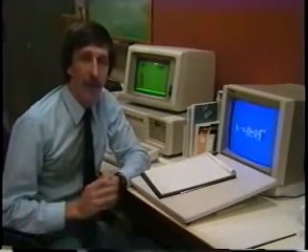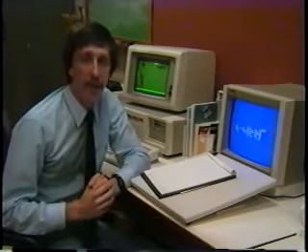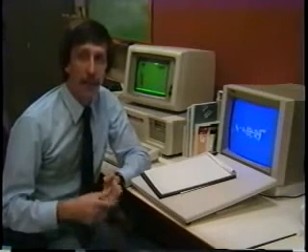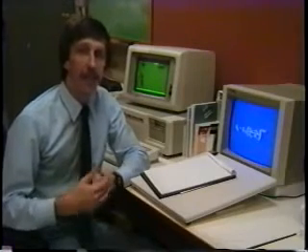Well, we're done with the flow test, and here I am back at the computer terminal again. Now is the time where we have the opportunity to do a lot more with the results of the hydrant flow test than simply plug them into an equation and predict the discharge at 20 psi. The first thing you need to do is to save the results. It doesn't really matter if you write on a piece of paper or store them on the computer, but nowadays there are some nice features in computer databases and spreadsheets where you can take the results and store them year after year, and then you can go back and look at the results. How did they change with time? What are these changes in time telling me about what's happening to the distribution system?